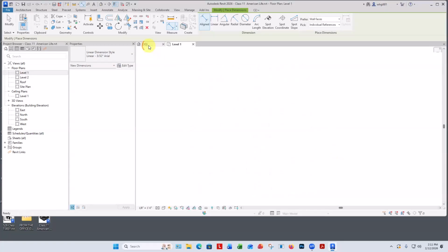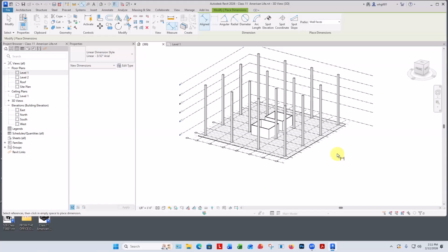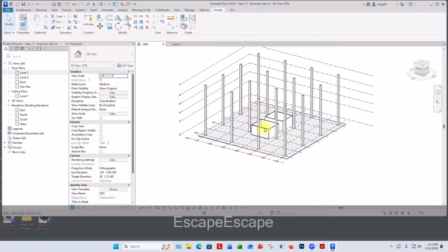Let's look at this in 3D. You know, we're drawing there on the first floor level, and by default, when you're drawing on a level, the walls just go up to the next one, because they mostly do. But we want these to go clear up to the roof level. You might have noticed when the Belknap Village dorms were going up, they just built those elevator towers straight up with nothing around them. And then the steel comes in floor by floor, and the floor is poured on top of that. So let's take these up to the roof.